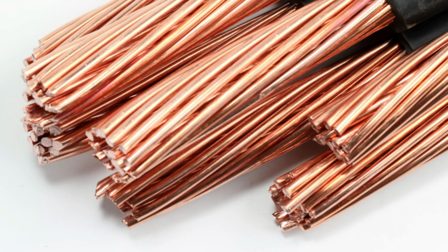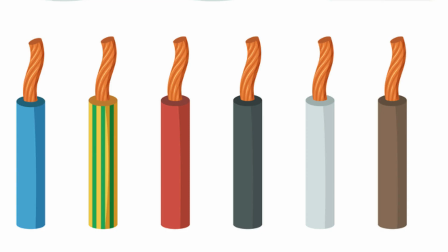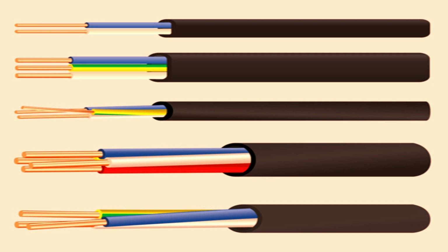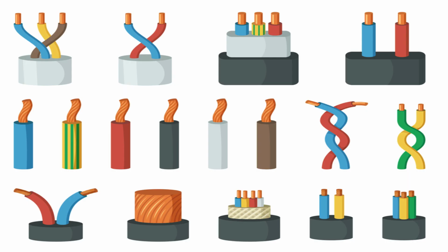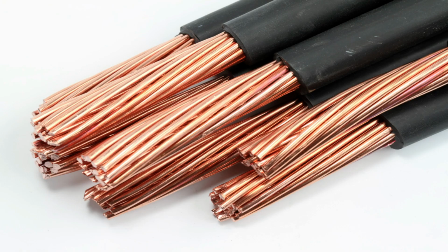They are majorly used for transmission and distribution purposes. But copper cables, on the other hand, are resistant to corrosion and are suitable for indoor and outdoor wiring. Copper cables also have a higher conductivity, specifically 40% greater than aluminum. Other than being expensive, they are available in all sizes, unlike aluminum cables. Copper cable size is even one third of aluminum with the same conductivity.